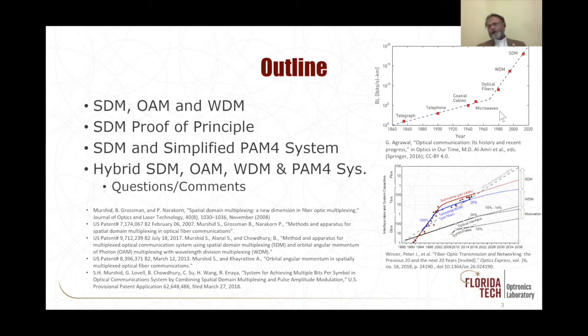Then we will show that SDM, OAM, and WDM, or the entire SDM system, can be combined with a simplified PAM4 system. What is a simplified PAM4 system? Instead of using dedicated DSP chips to generate the PAM4 signal levels, we found a way to use incoherent addition of laser beams to develop the PAM4 signal.